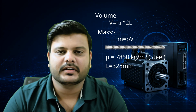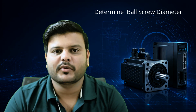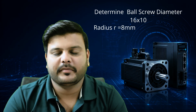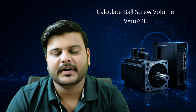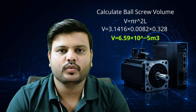Converted into meters, it becomes 0.328 meter. Now determine the ball screw diameter. We have previously selected a 1610 ball screw, so our diameter is 16 and radius is 8 mm. Convert this 8 mm radius into meters, so it becomes 0.008 meter. Now calculate the volume of the ball screw. We know the formula V is equal to pi r square multiplied by L. Substitute the values in the formula, so we get volume 6.59 multiplied by 10 raised to minus 5 meter cube.